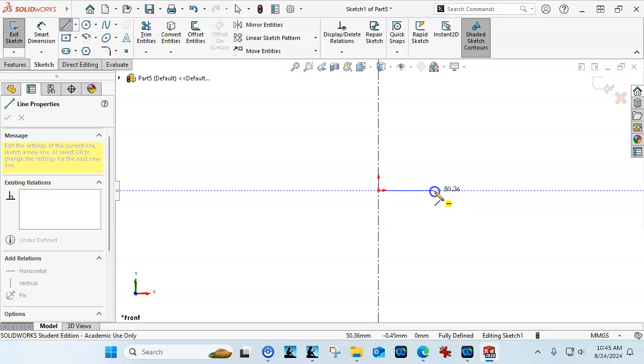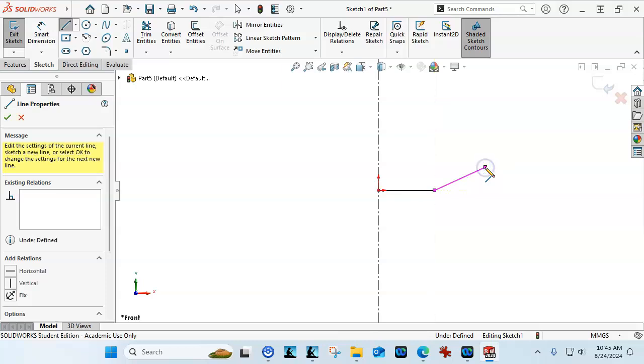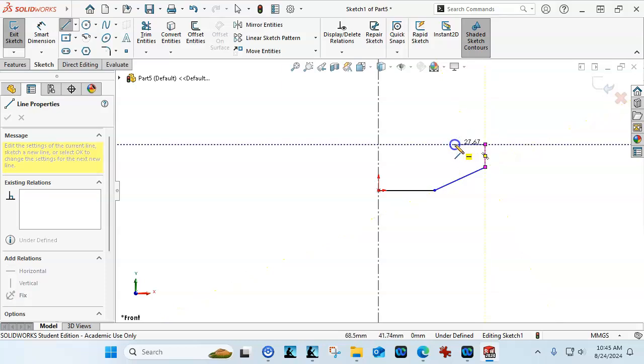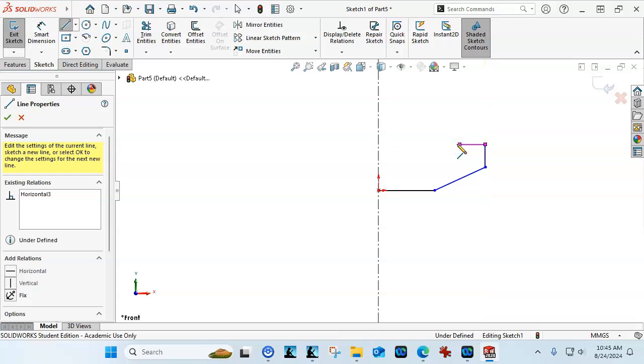All right, so I'm going to start with the click drag, and we'll generate those geometry. And there's not a lot here to look for in the way of inferred relations. Just be aware there's a perpendicular, there's a collinear, and there's the vertical. And then we're going to bring that back a little bit. And in that case, we have the horizontal. We see the inference line going to the vertical, but it's in white, which means that it's not going to be assigned.